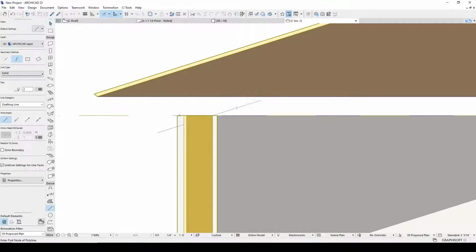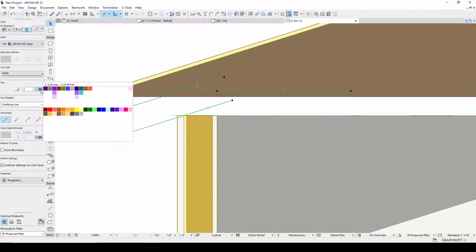If I'm doing a trussed roof, I'm going to take that same line, and it depends. Usually I have the truss company measure the outside of the plywood. And this is, say, 2x4, so it's 3.5 inches. And then the ceiling member, let's make these lines easier to see.